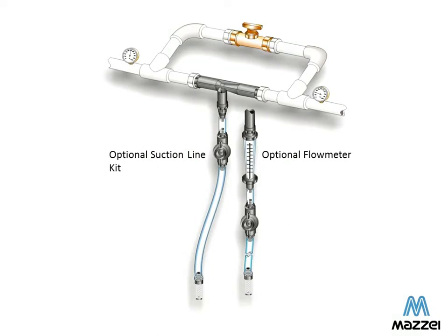The injector may be on the bypass, or the injector may be in the main line. This is just an example of that. If you have a large motive flow as compared to the amount of water that you are bypassing around the injector, then it might be to your advantage to put the injector in the main line and make your bypass system the part that has the pressure reducing valve. And then again, it would function the same way.